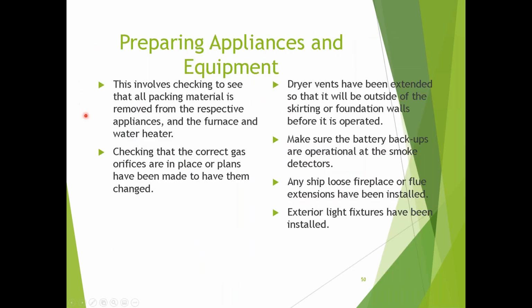When it comes to preparing appliances, one of the things you want to do is make sure that you unpack the appliances, whether it be a stove or refrigerator. When I say unpack, a lot of times the packing from the manufacturer of that equipment will have the cardboard protection, the plastic to prevent it from getting scratched. You want to make sure all that gets removed. You want to make sure that the appliances are set up for whatever gas is going to be used, whether it be natural gas or LP gas.